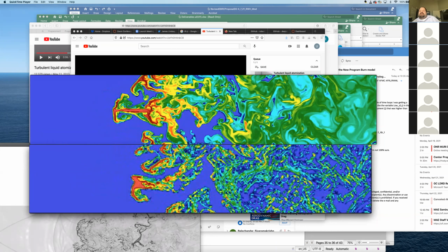And so if you were to calculate the resolution you would need to resolve all of those droplets, now granted there is a size distribution of those stripped off droplets, but if you were to capture say 90% of them, your grid size would be on the order of 1 million grid points cubed, in order to capture the droplet dynamics, and the advection of the shockwave, and then its effects.